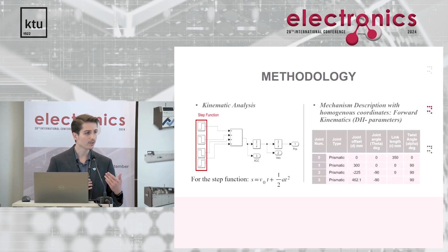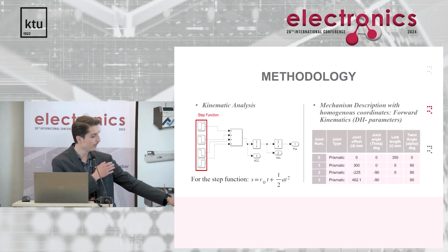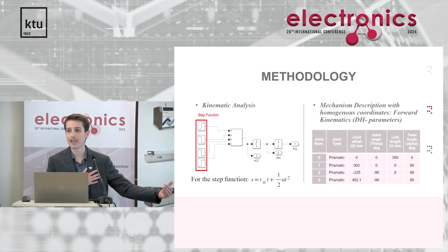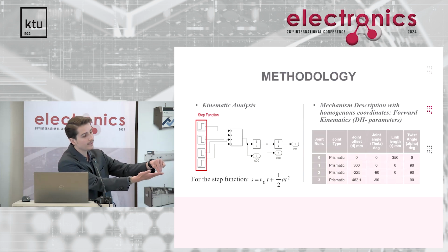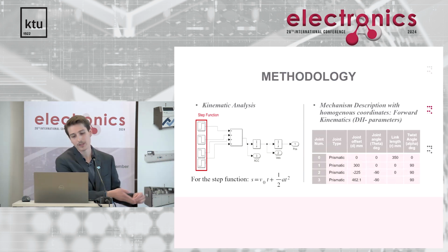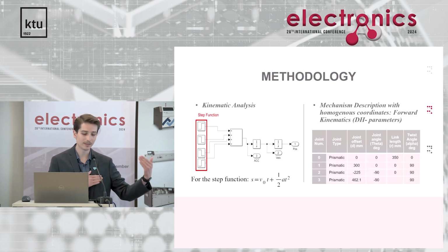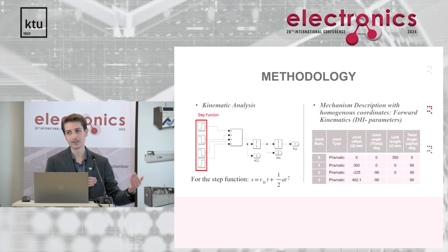In case of joint coordinates, for example, if we have a robotic arm, we can see the different kinds of joint angles here, here, and here. The actual values of the given joints are the joint coordinates, and the world coordinates are the 6 degrees of freedom of the end effector. During the motion of the robot, there is a conversion between them. So joint coordinates are converted into world coordinates and converted back into joint coordinates. In this case, we can distinguish forward and inverse kinematics.